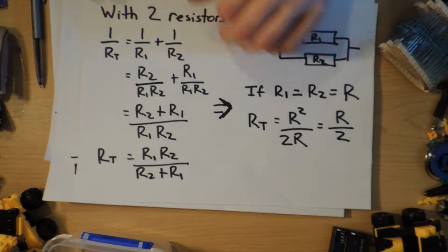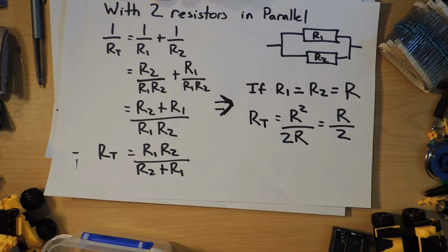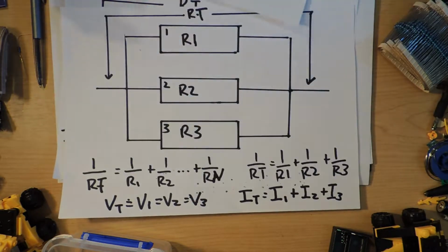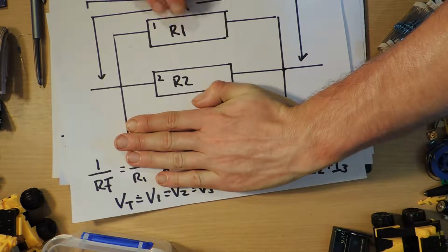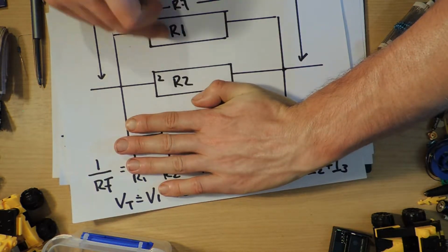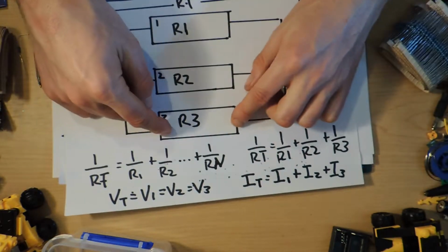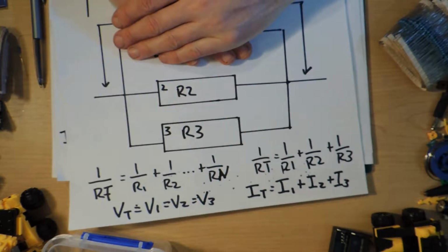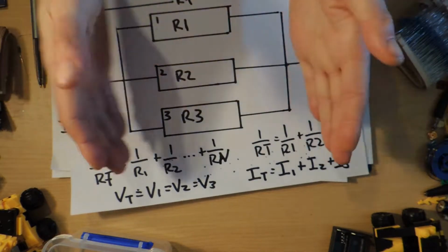And I think the important thing is that there's a simplified way of doing it if there's only 2 resistors in parallel. And the neat thing is that this basically covers all the cases of resistors in parallel, because you can start off by working out the total resistance of this thing by ignoring this one, and that gives you a resistance for just these 2 going across here.